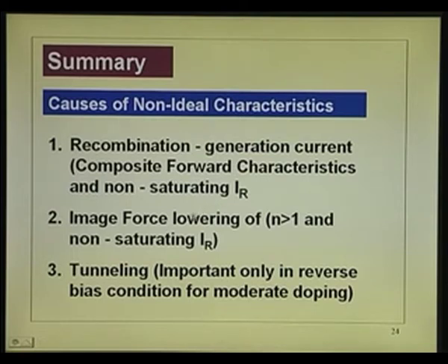If you take silicon, it can affect to some extent, because the J due to thermionic emission and this, the difference is less. So, it can become more dominant, or it will show up as you go to larger reverse currents, but in gallium arsenide you do not have to worry.